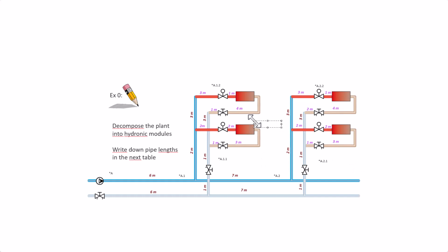Okay, let's add some information. There is 2000 liters per hour running through this terminal unit with 10 kPa of differential pressure. That is something we know, and it will be the same for all the four branches. So let's use this as information to work with. We have a heating installation with standard water, so no additives. Voila.